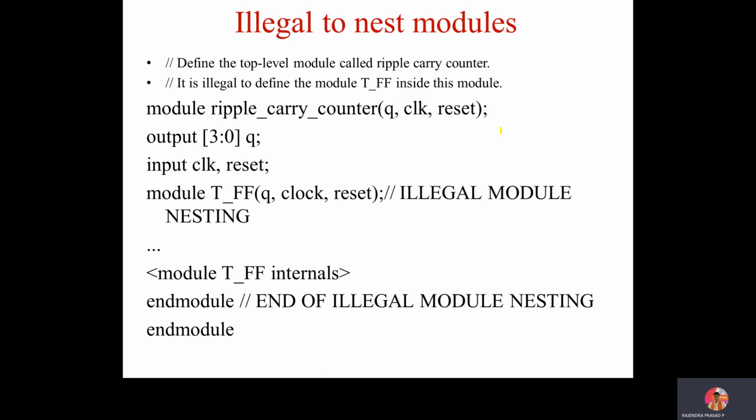See, if you miss the semicolon, then again it is an error. If you don't give a vector declaration, then also there is an error. If you write a module within a module, then also it is an error. And if you don't declare a variable, for example in the variable list you have given A, B, C, and here you are writing input clock, reset, then that is also an error. So these are all the different sets of illegal statements which will create an error. Sometimes it will be a logical error, sometimes a syntax error, sometimes a variable insertion error.